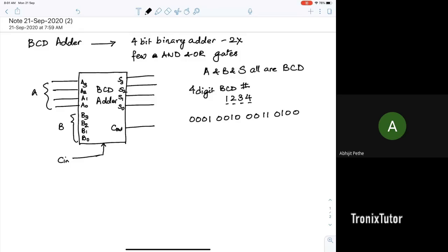And so how would you implement it? Suppose I want to implement a 4-digit BCD adder. Then I'll individually implement each and every 4 bits as a BCD adder and use the C out of the first. So for example, this will be one BCD adder, and I'll take the C out of this adder and push it into the CN of the next adder, and so on and so forth. Designing something hierarchical makes it very easy to blow this up to a larger bit length.